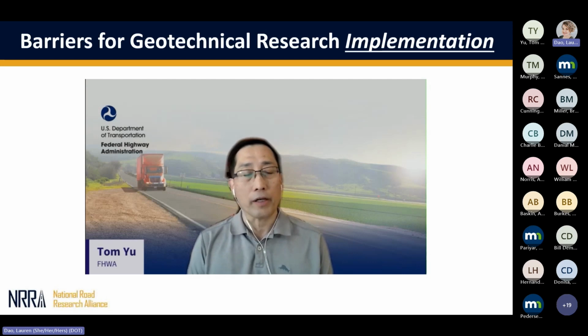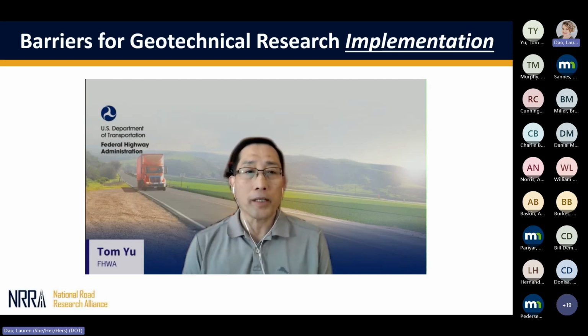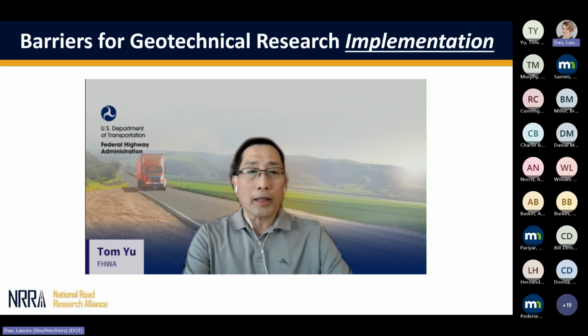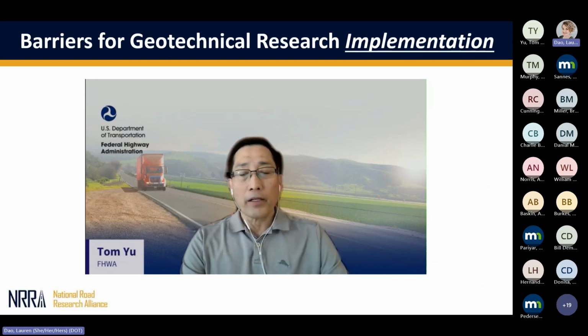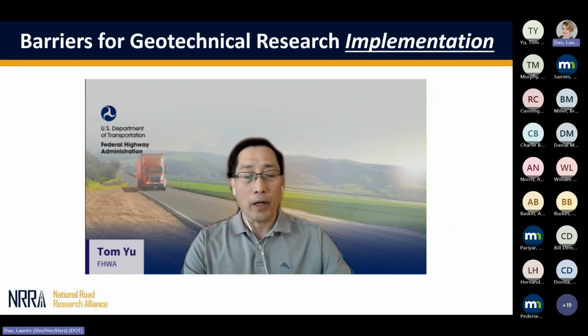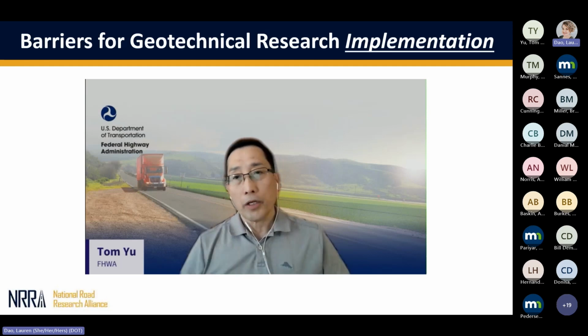The stiffness and strengths are important for those types of analysis. So when we do that type of analysis, effects of foundation don't really show up very well because the surface layers are so much stiffer than the layers underneath. They completely overshadow whatever we place underneath.